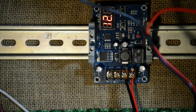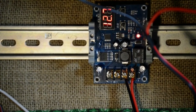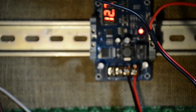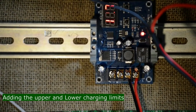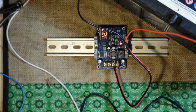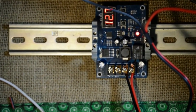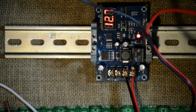So this happens regardless of what battery you put in. So using the buttons below the screen, we're able to set our threshold to say this is when I want you to start charging at this voltage, and the other one is when you want it to stop. And again, realize that there's nothing connected at the in stage. We're still at the battery voltage, right?